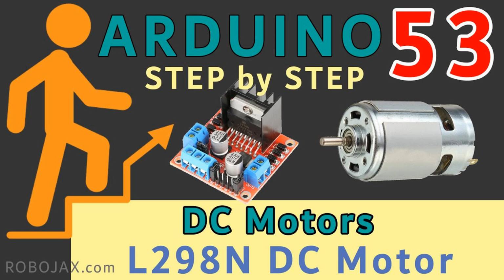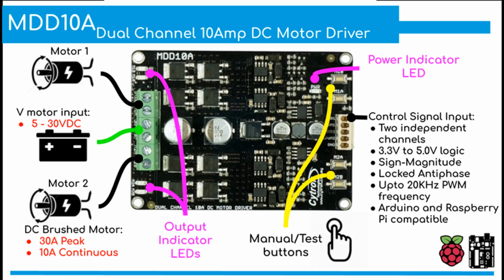Operation: by varying the current to each motor winding in smaller steps, the driver enables finer control over motor position, which results in smoother motion and quieter operation. Advantages: smoother, quieter motion with higher positional accuracy. Microstepping can reduce mechanical resonance and vibrations. Disadvantages: increased complexity in driver design and may require more current to maintain the same torque.